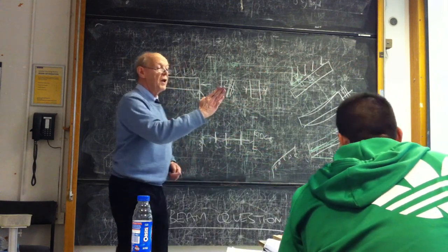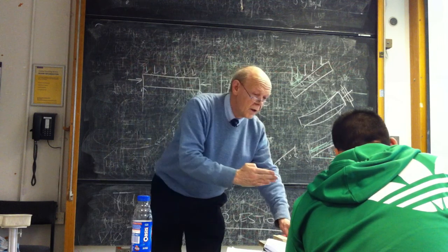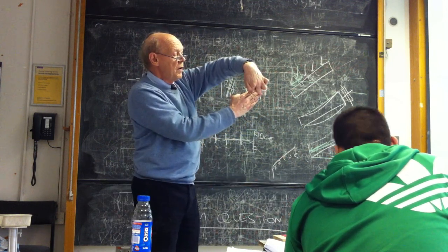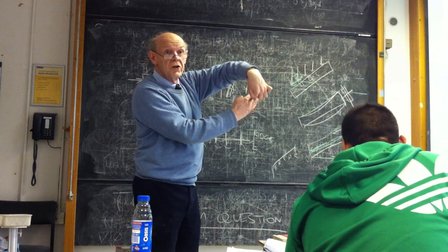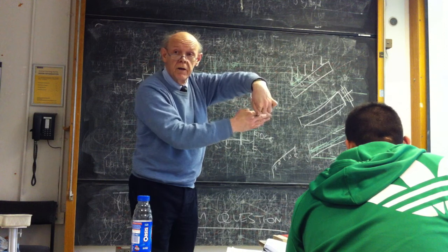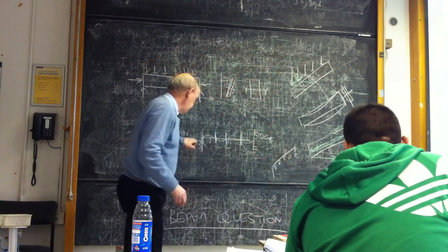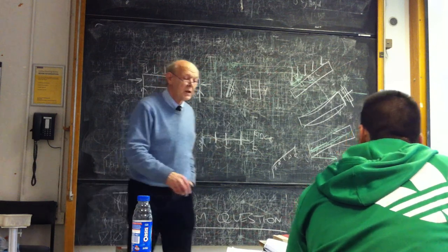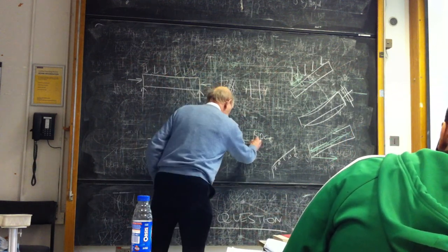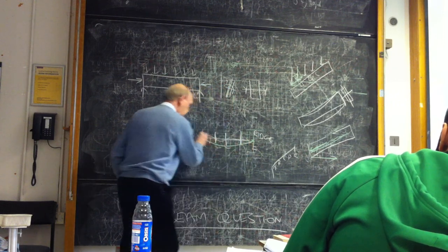If it wants to twist, and it's got something coming in from each side, this joint isn't going to stop it from twisting. It can stop it from moving sideways, but it won't stop it from twisting. So this thing is restrained against buckling like that, but when it comes to checking twisting, which is lateral torsional buckling, it's only really properly restrained there and there. So the lateral torsional buckling length is something like that.